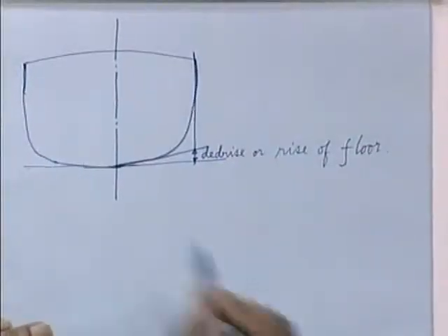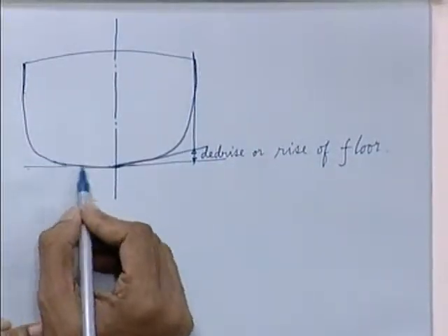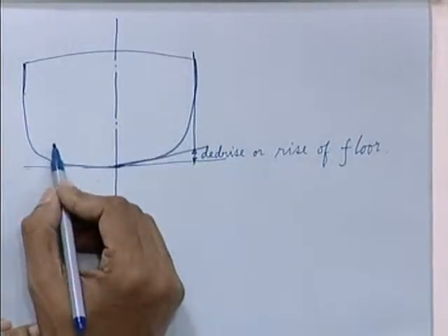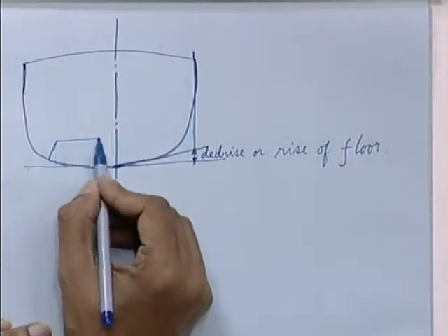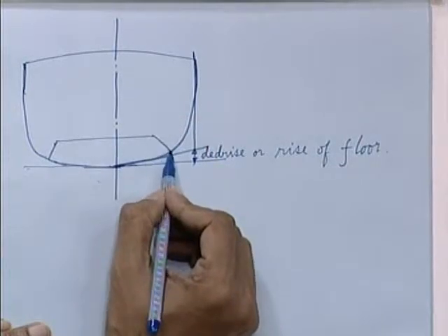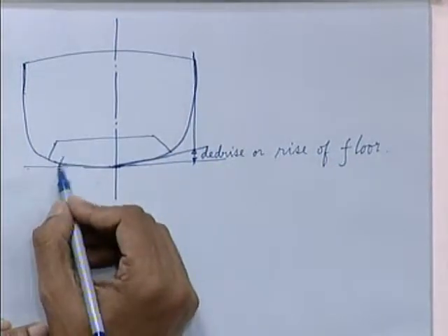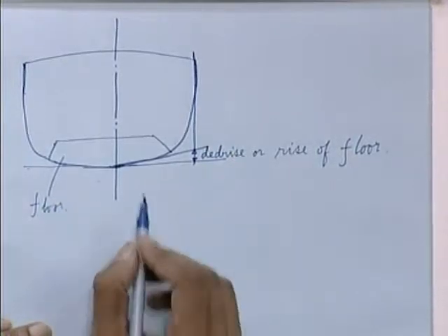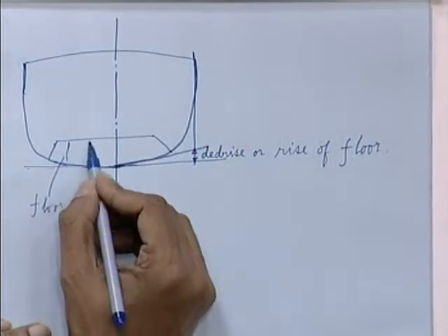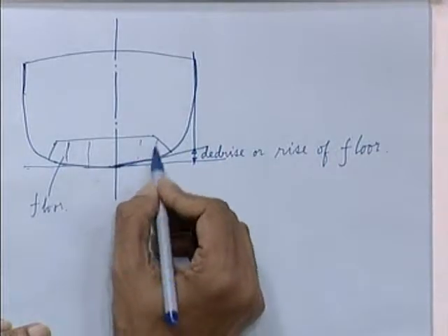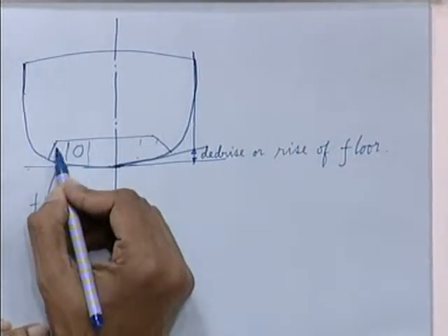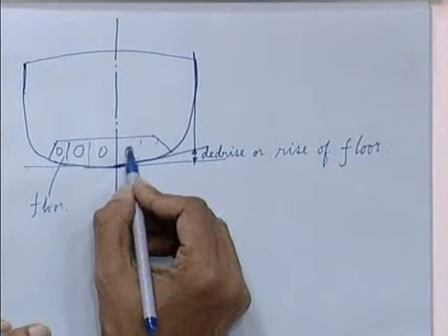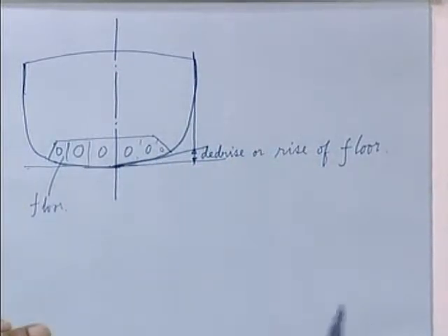In naval architecture terms, floor does not mean the flat floor that you can normally see in a room, but those are vertical structural members. They are called floors. These floors have stiffeners which are called brackets, and inside you may have lightening holes through which your pipes will pass.